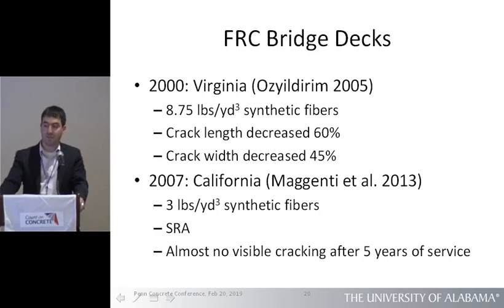As some particular field studies, and there's more listed in the actual document, in 2000 in Virginia, 2 companion bridge decks were constructed side by side, one with fibers and one without. The dosage of the fibers was relatively high, 8.75 pounds per cubic yard of synthetic fibers. After 5 years, the crack length in the fiber reinforced bridge deck had decreased 60% relative to no fibers, and the width of those cracks was 45% smaller compared to no fibers.